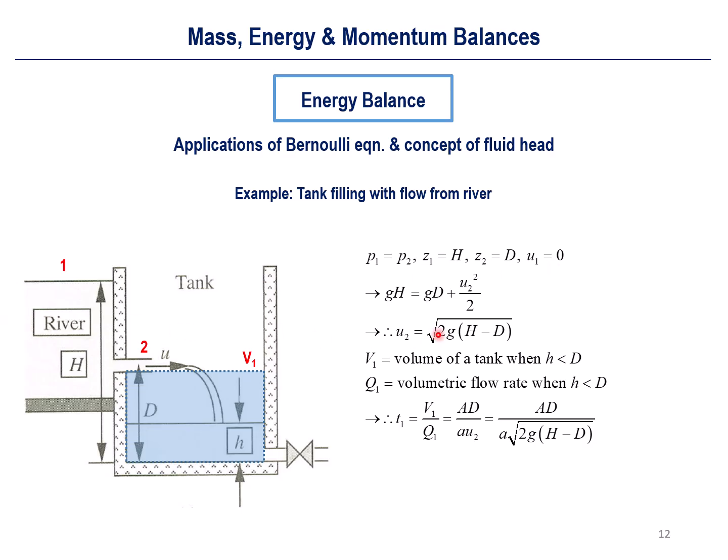And that's why we can apply the generalized Bernoulli equation. When you take this situation into account, the only remaining energy term is just potential energy. But at point number 2, we have potential energy and kinetic energy. Anyway, U2, which is the outlet at the floor, the velocity is square root of 2g times the height difference.